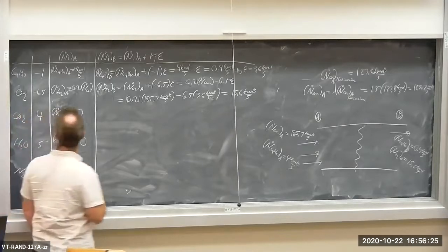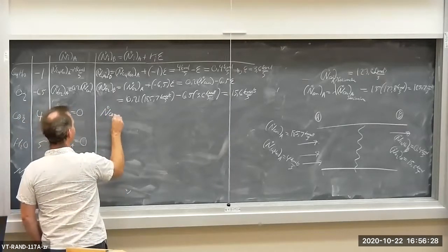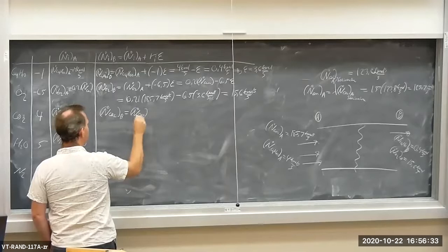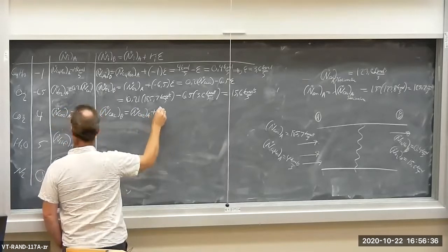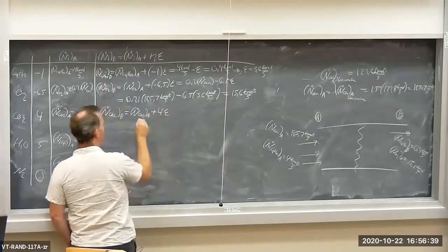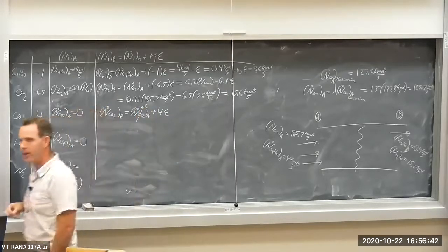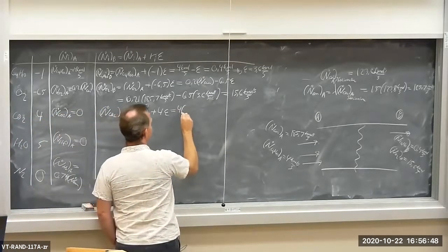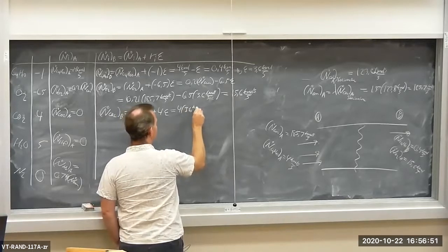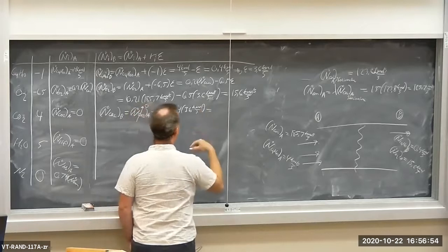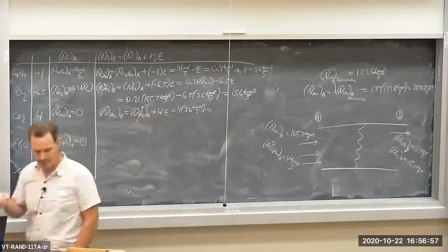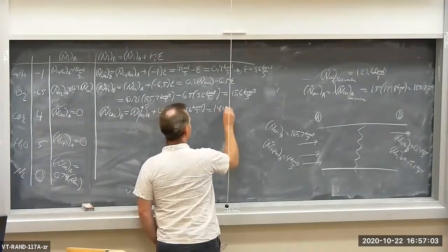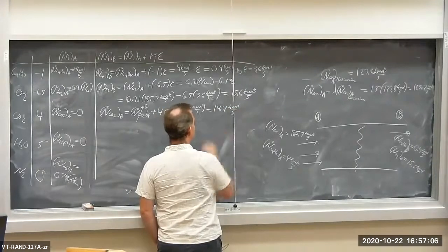Let's do the CO2. n dot CO2 in the products is equal to n dot CO2 in the reactants plus the stoichiometric coefficient times the reaction coordinate. There is no CO2 in the reactants, and so I get 4 times 3.6 kilomoles per second, or 14.4 kilomoles per second.